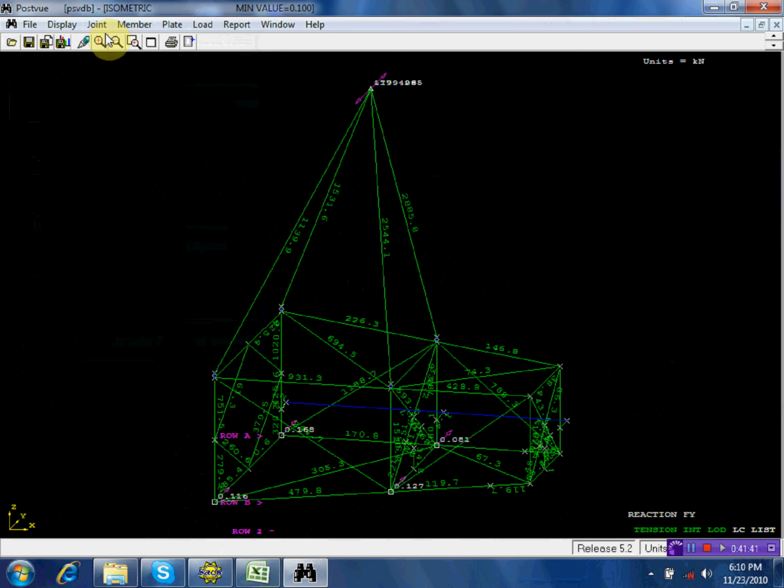Tension only. Gap element actually doesn't need an input file. You can model it inside, or you can model it outside. The loadout for topside, that's outside. That's why we need an input file. If you want to make it in the model, you can do that. So like this, I will use gap element. This is how to model gap element inside this model file.